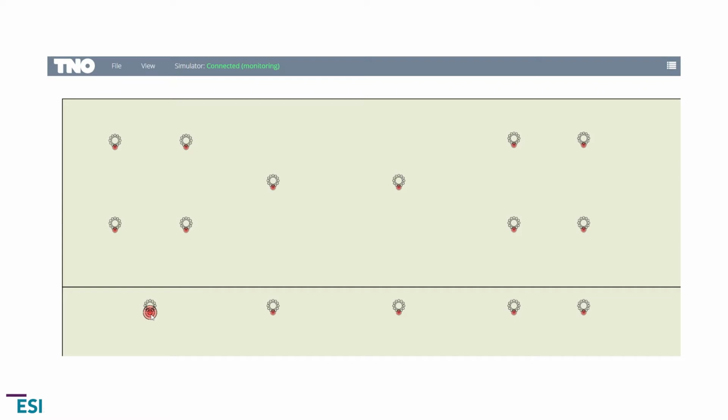But we have the scenario, we enter the corridor and we go to our working space, as I explained in the presentation. You see that the light turns 100% here and the other places 50%. I walk to my actual room. This workspace gets 100%, this one 50%. You see that the lights turn off in the corridor, so it's independent. If I go here, no lights will turn on in the corridor, so there is no linking between the rooms.